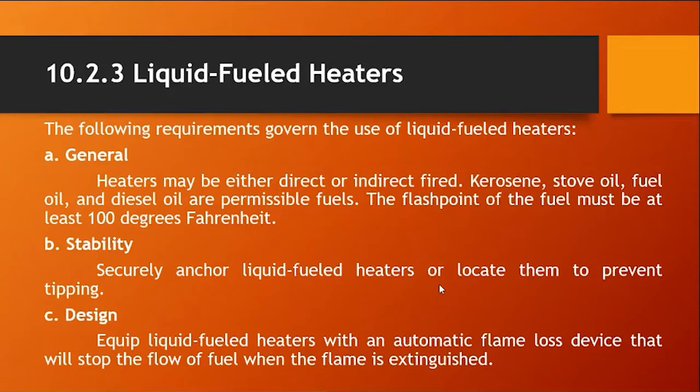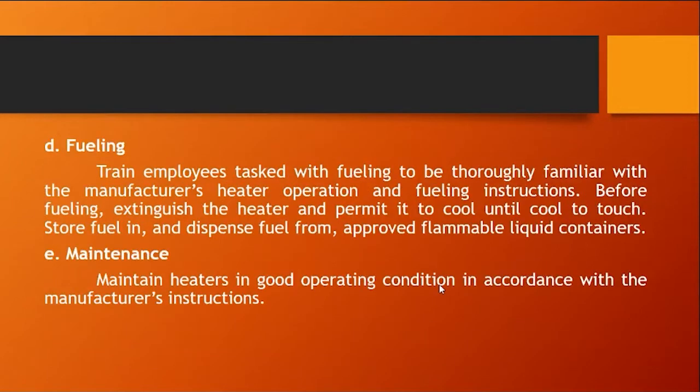Stability: securely anchor liquid fuel heaters or locate them to prevent leaking. For the design, equip liquid fuel heaters with an automatic flame loss device that will stop the flow of fuel when the flame is extinguished. For fueling, train employees tasked with fueling to be thoroughly familiar with the manufacturer's heater operation and fueling instructions.